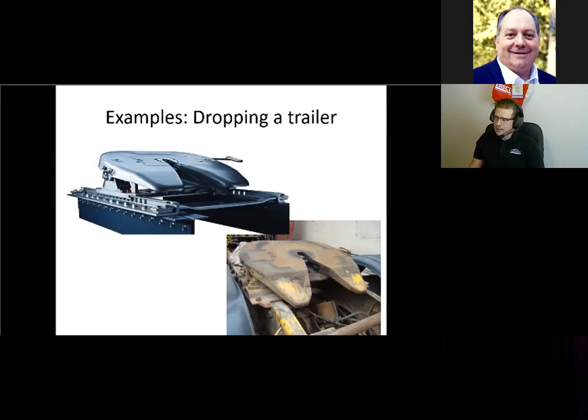Have a mechanic come out and do an analysis. And here you see that now the tactical labor is getting involved. A trained professional mechanic comes out, has a look at the fifth wheel, has a look at the trailer, determines that there's 4 bolts that have been sheared off, and looking at things like the powder coating and other things, it seems like this fifth wheel was only attached with those 4 bolts. And normally they have something like 12 or 14 on each side,